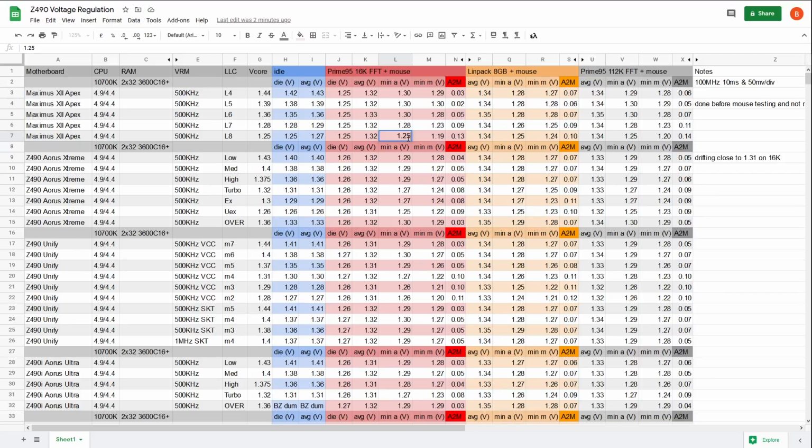If we were measuring all the way at the actual die itself, we would maybe see more undershoot. Here I'm seeing a 70 millivolt gap; if we were measuring at the die sense, it might be like 80 or 90 millivolts. It's not a huge difference on some motherboards where I have actually done die sense versus relatively close to CPU measurement testing. The difference isn't massive, but it is there. So to simplify, let's just say the voltage would be undershooting down to 1.27, whereas here this would be bottoming out at 1.23.